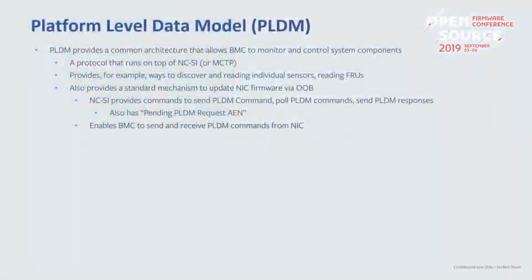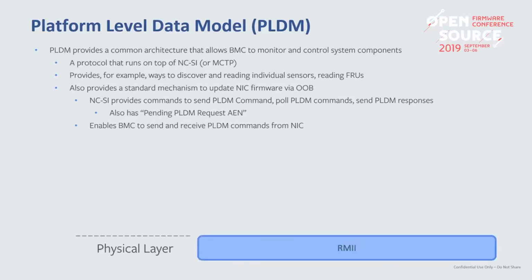Here's a recap. PLDM is not the only way to do firmware update, but it is a DMTF standard, which gives us a standard way, from both the BMC and the device point of view. It provides a standard protocol to do firmware upgrades. It defines a protocol that both the device and the BMC can follow.